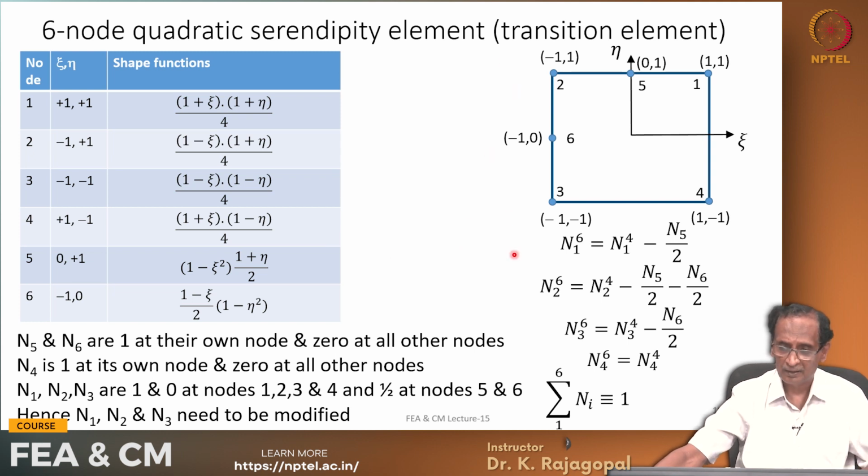So, in the eta direction there are 3 nodes, so we can write like this, and if we evaluate N1 and N2, they are half here and they are also half here. Then N3, if you evaluate N3 for the 4 node element here, you will get half, and N3 along this line is 0, and N4 is 0 if you evaluate along this line or along this line.